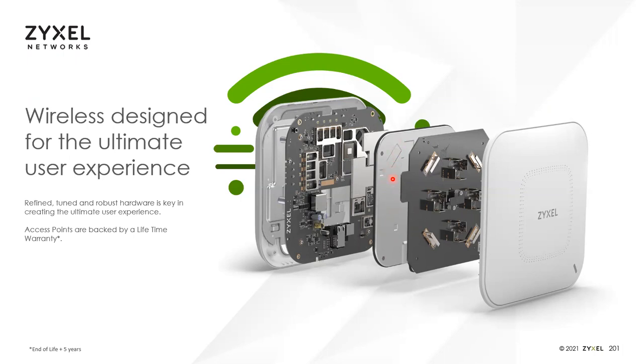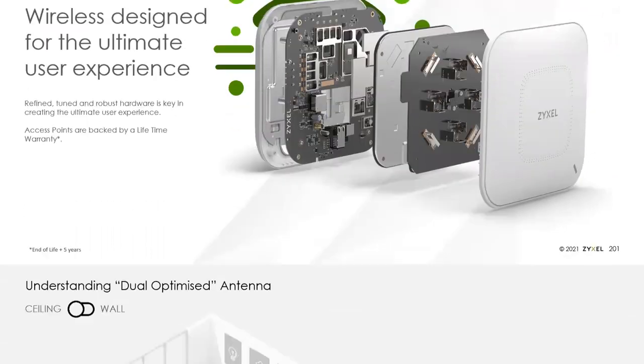So this applies to all of our access points, which come with a lifetime warranty, which at this point is all of them, from the cheap little NWA1123-ACv3 all the way up to our WAX650S. They all follow this design philosophy. Another thing that we do differently here is we only use solid state capacitors. There are no electrolytic capacitors. So that removes one more common cause of failure on a solid state device like this.